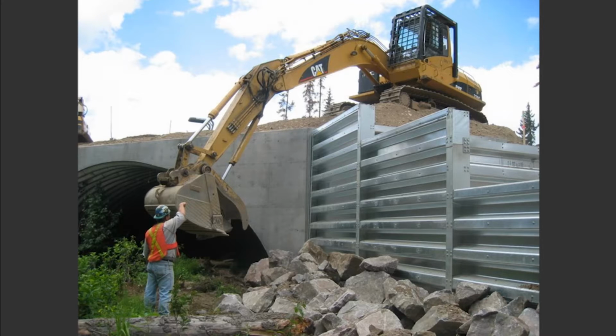Again, another photo of bin wall in the wing wall application for a bridge plate culvert. Often this is used in conjunction with either a cast in place head wall or an anchored steel head wall, as I showed before. Often cast in place is going to be a good solution if you're expecting high debris flows through the culvert. It can really be the best method of protecting the bridge plate structure.